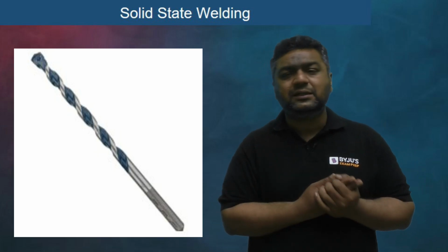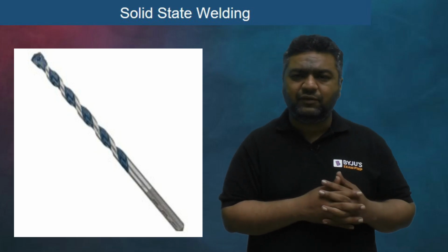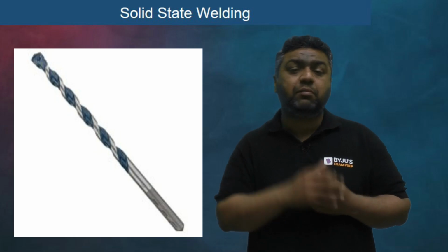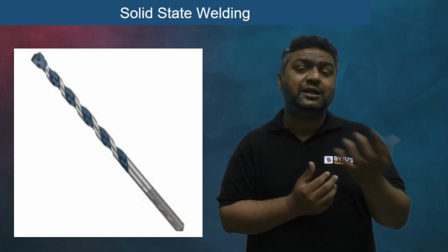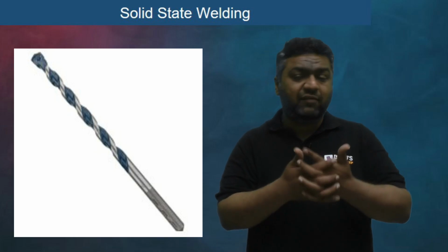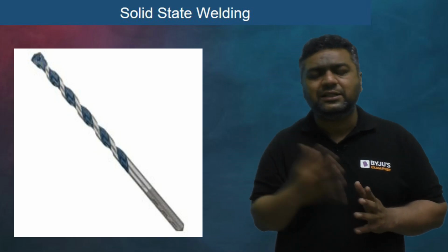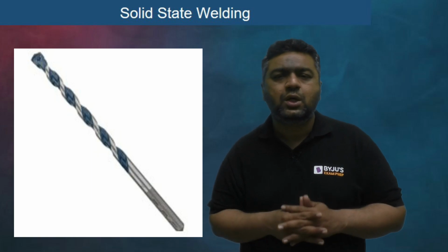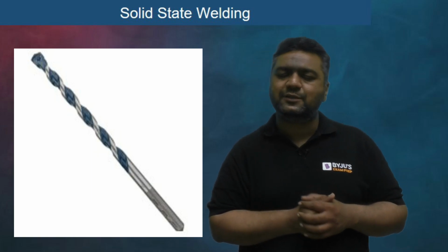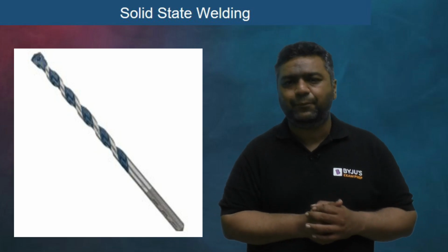Drill bit is made up of some hard material, whereas shank is made up of some tough material. To integrate both the properties, we are having different materials. For cutting edges, we need hard materials. So my dear, they are also joined with the same process, and this process was friction welding process.